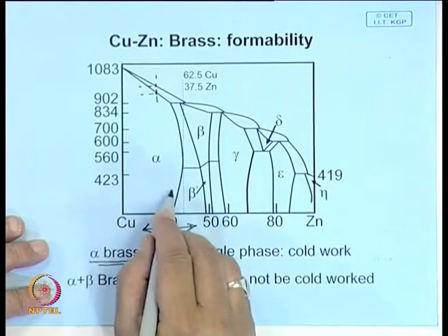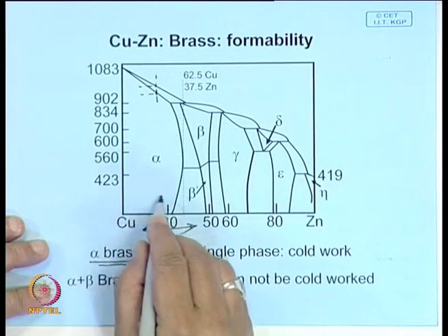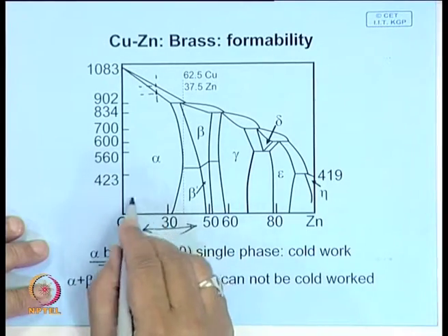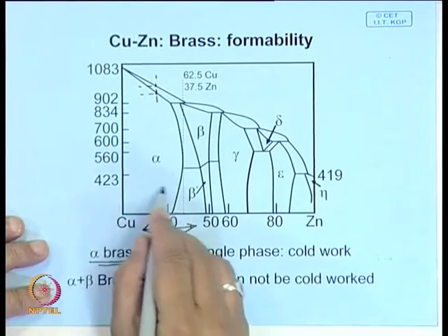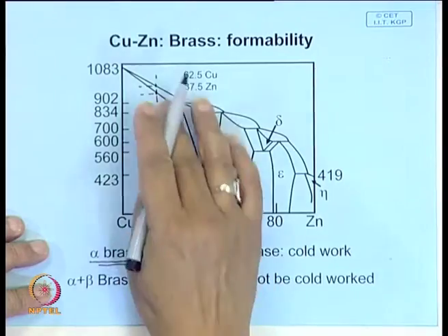Cold work, anneal, and at the final stage, if you want higher strength in the material, the material can be left in the cold worked condition, or you can at best give a stress relief annealing treatment.